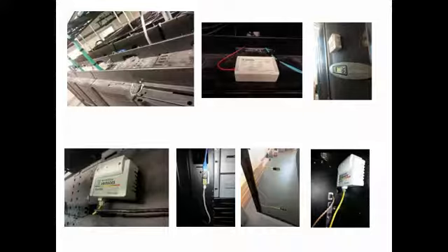And then on the upper right is one of the sensors just stuck to the edge of a rack. On the lower left is one of those sensors, and coming out of it you can see a Cat5 cable on the bottom, and that is going to a daisy chain of temperature sensors, which is shown on the next picture. So the Cat5 cable comes in the top of the sensor, and another Cat5 goes out of the bottom, and those are daisy chained together, up to 8 per RF node. It's possible to do a few more than that, but we don't recommend it.